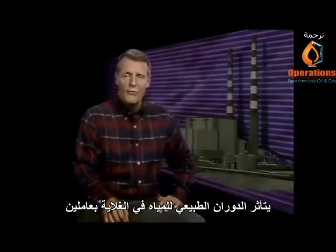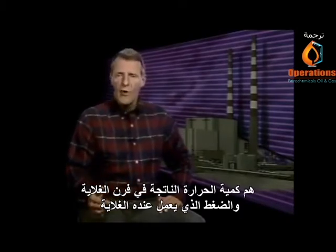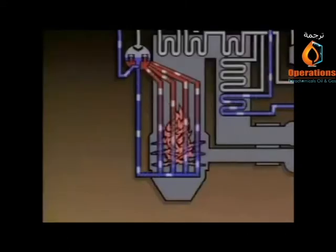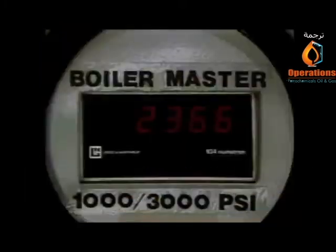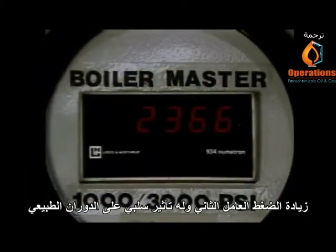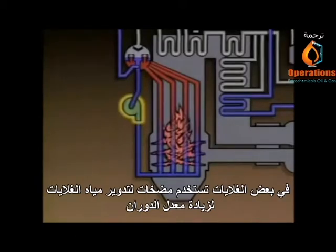Natural circulation of water in a boiler is affected by two factors. They are the amount of heat produced in the boiler furnace and the pressure at which the boiler operates. For example, raising the temperature in the boiler furnace increases natural water circulation because it results in a greater temperature difference between the water walls and the downcomers. Increasing the second factor, pressure, has a negative effect on natural circulation because as pressure increases, the density difference between water and steam decreases.